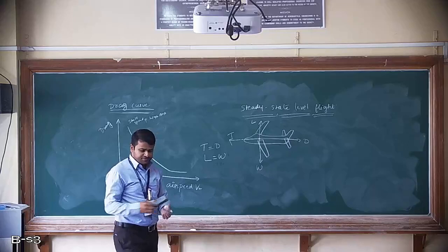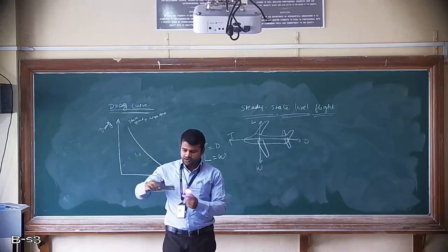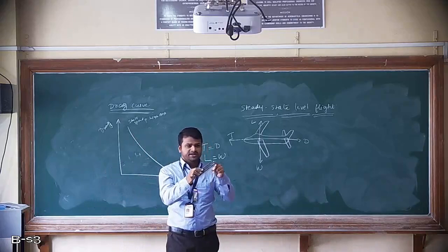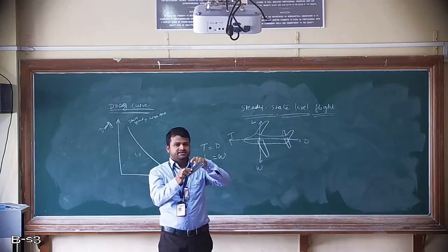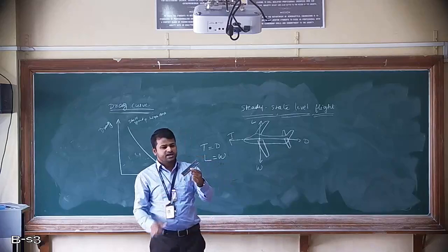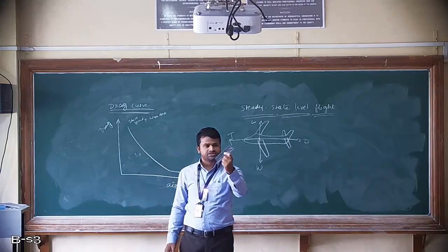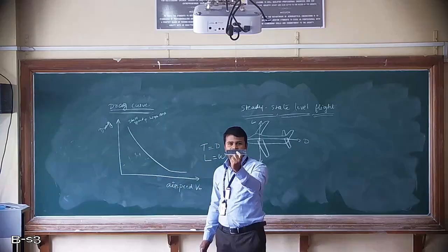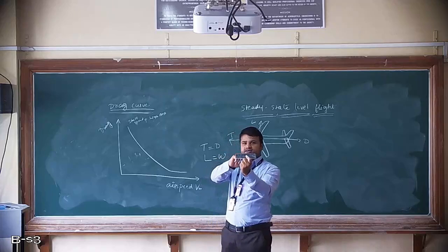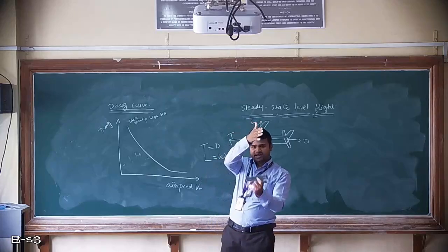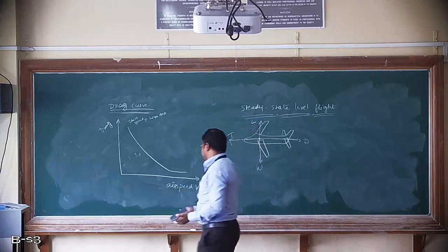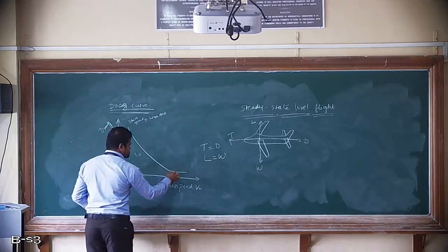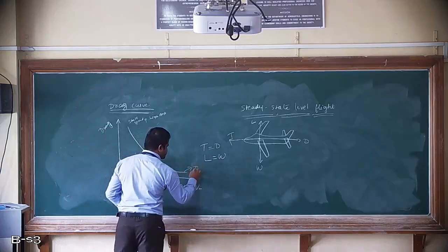It's like this. The aircraft is initially on the ground, running, taking off, where your angle of attack increases. Due to that, induced drag is created. After a certain time it will reduce its nose down. That means it will reduce the angle of attack and become straight, where lift generation is now little. That means the induced drag is decreasing with respect to your airspeed. So now I will write this: this is induced drag, or drag due to lift.